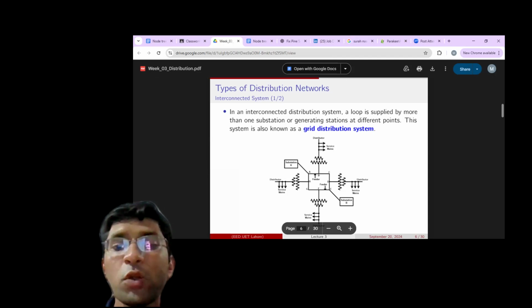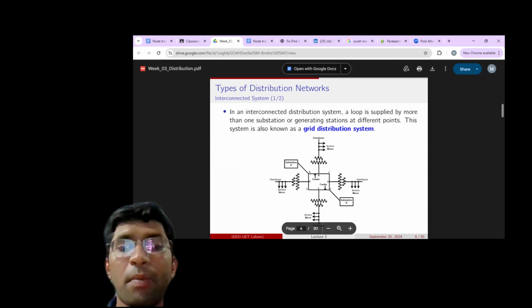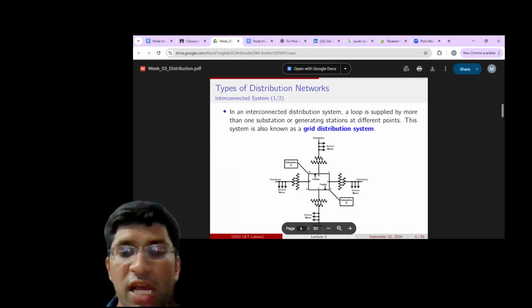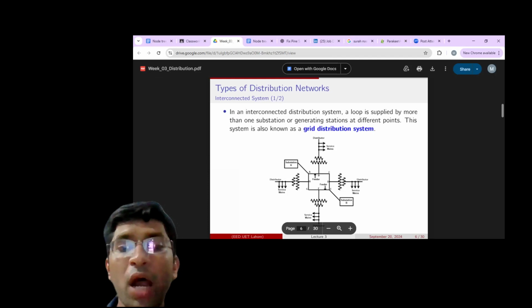So, what do you think about the protection and reliability? The US utilities measure reliability using SAIDI and SAIFI indices. For example, utilities in states like California and Louisiana often report higher outage duration due to storms and wildfires, while utilities in New York and New Jersey perform better because of more robust ring and network distribution.